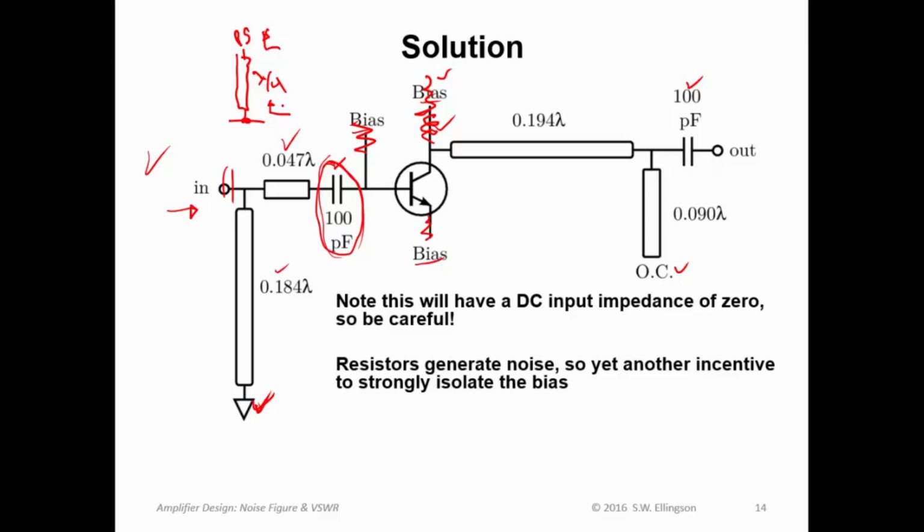So it is fairly common to see in very high frequency LNA designs and amplifier designs generally structures like this that are being used to provide RF and DC isolation. And the reason is because this structure does not require an inductance and it does not require a resistance to isolate those two things.